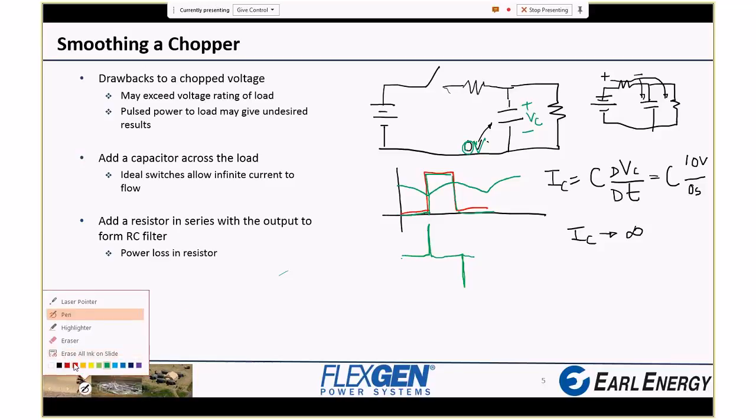So the low-pass filter is extracting some of this low-frequency information, which is the averaging effect you want. But it's not perfect, so it does still leave some high-frequency content on there, but certainly not as much as before. So that makes the no voltage to your load problem go away to a degree. It makes the over voltage problem go away. The pulsing motor problem goes away to a degree when you do this.